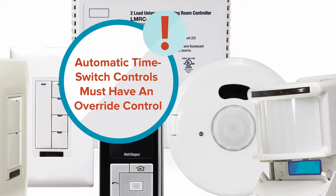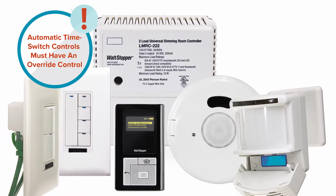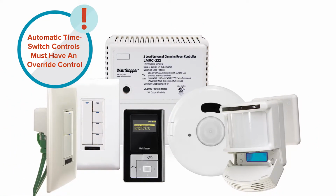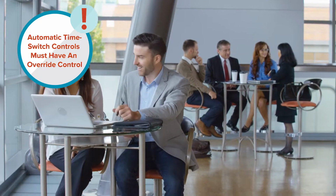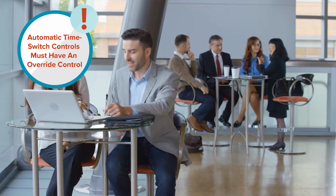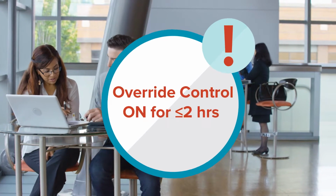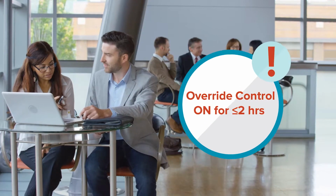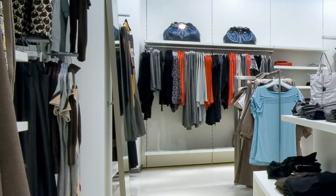When an automatic time switch control is used to comply with the automatic shutoff requirements, the control is not responsive to the presence or absence of occupants. Therefore, the automatic time switch control must incorporate an override so occupants can still use the lighting. The override control must allow the lighting to remain on for no more than 2 hours when an override is initiated. However, there are exceptions to the override time limit.